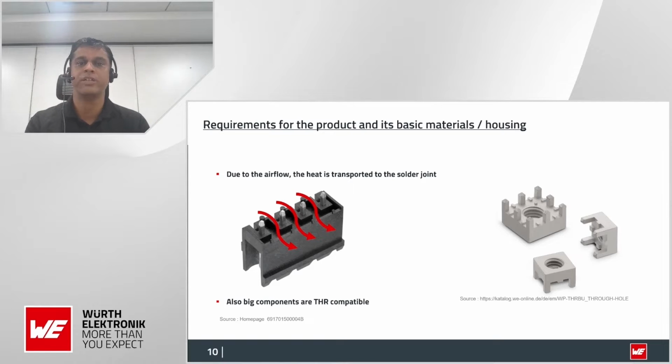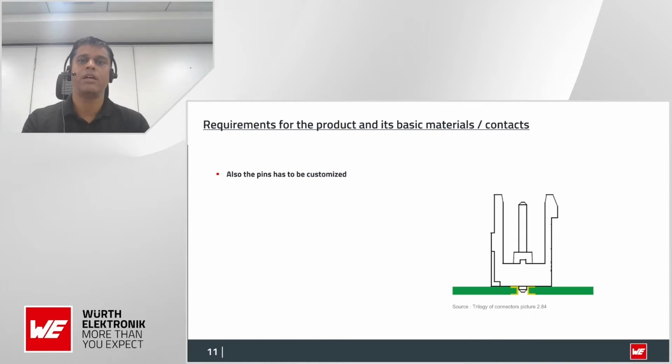So you can see the pins of the connector, there are standoffs there. This allows thermal efficiency, by allowing the air to pass over these, so the thermal stress can be avoided. So till now we have seen the design changes with respect to materials and the housing. Now we discuss the pins. So the first question is, do we need to customize the length of the pin?